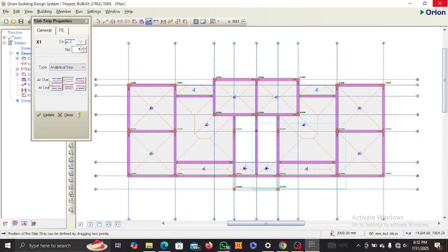So what this means is, for this strip, the first one here means that if there is continuity, there's a slab and then there is a beam and then the slab. Now this one means that it's just a beam into it. And this means a cantilever. If you hover around, you're going to realize what it means. It means that there's a slab. Hold here, it means that there's a bulb. That means it's at the end of a beam. And this means it's a cantilever for your start and at the end.